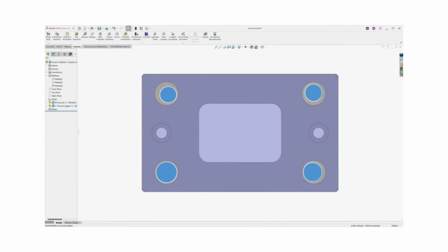Instead, we need a variable size gauge, one that could first adjust to the different pin sizes, and then we can see where the position of each pin is. So this makes inspection more complicated and expensive because it requires specialized equipment. Basically, a CMM would be needed to ensure that the part meets the positional tolerance across all the possible sizes.